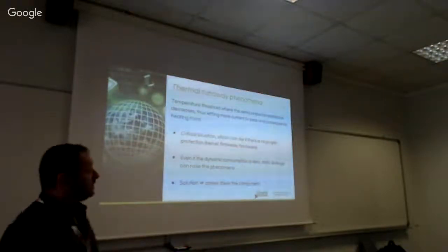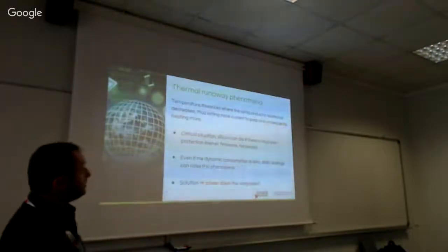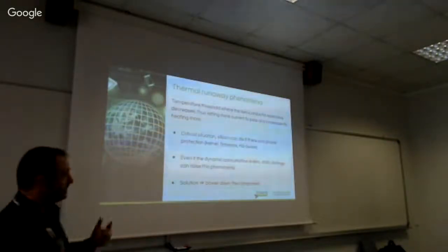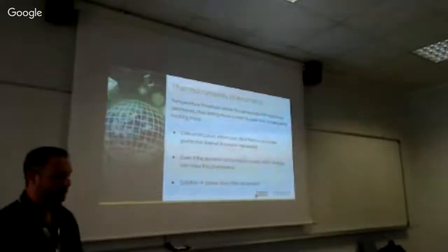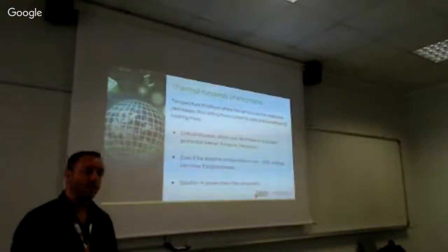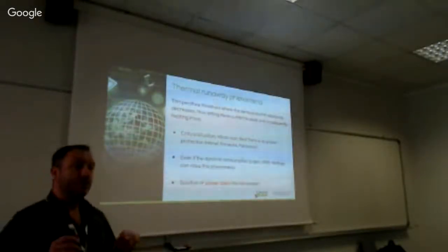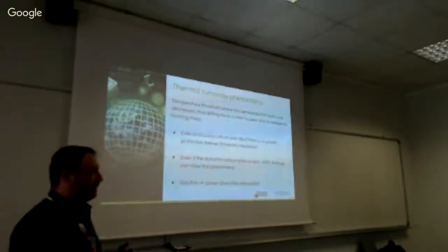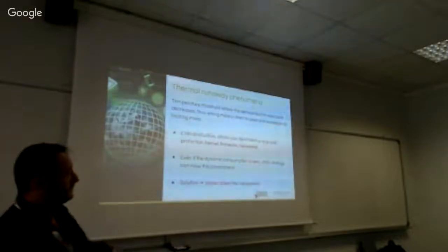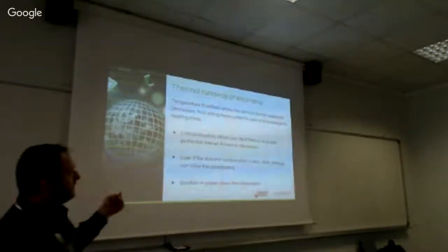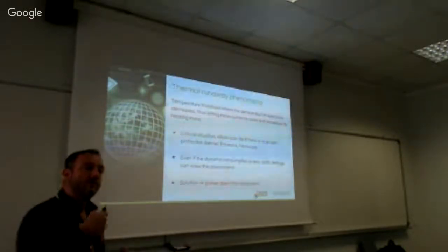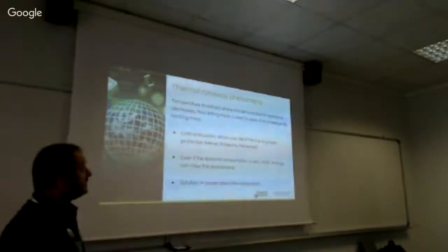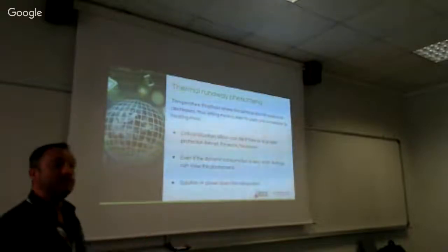And then we have a third phenomenon, which is thermal runaway. In this situation, the component is heating more and more. And even if we stop using it, for example, reducing the frequency to 0, because of the silicon, the current is still growing inside and it's still dissipating more power, heating more, and the temperature is still increasing.